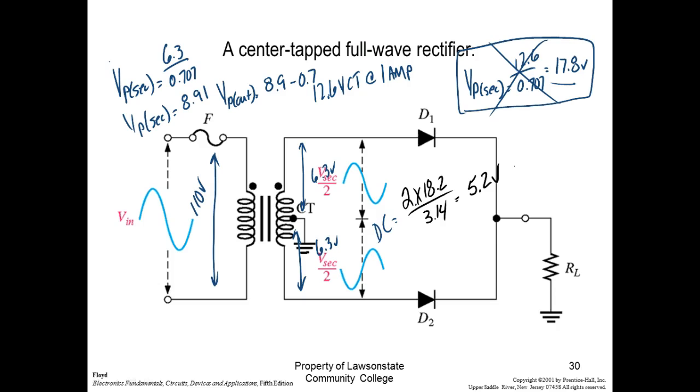For some reason, since these things are drawn side to side, some people see this as a parallel. Somebody in this class is going to hook these in parallel. If they're in parallel, folks, both sides are connected together. Is this cathode connected to the other cathode? Yes. Okay. Does that mean they're in parallel? No. To be in parallel, both sides have to be connected together.